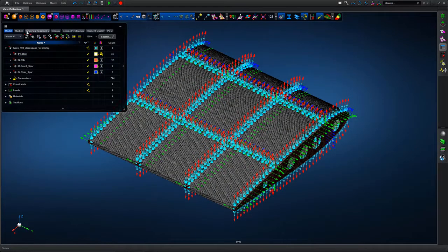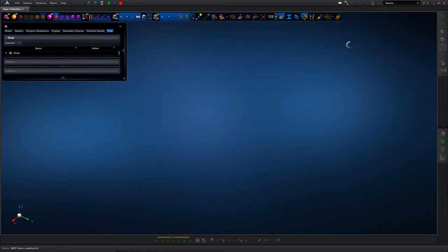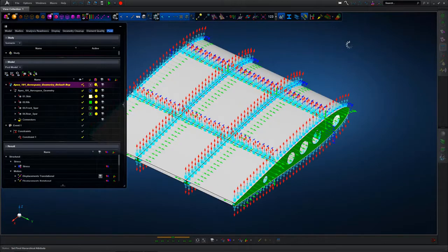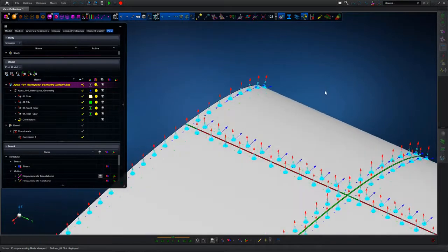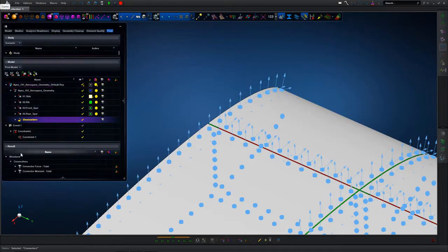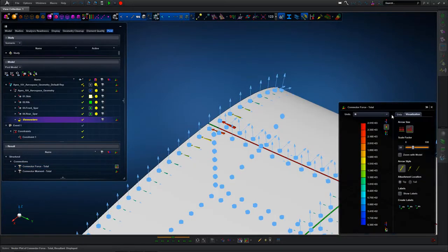So turning all of those fasteners back on into view and performing some post-processing. So we've actually run this already, and looking at some of the output, we can see again when the model comes through, we've got the mesh topology, the element edges turned off, so we can see the connectors are displayed in the post-processing environment as well. So we've got a good handle on what the pertinent directions are in terms of shear and axial force, setting the connections as the plot target, and then we can start to look at the vectors as they come through in terms of the joint interfaces.